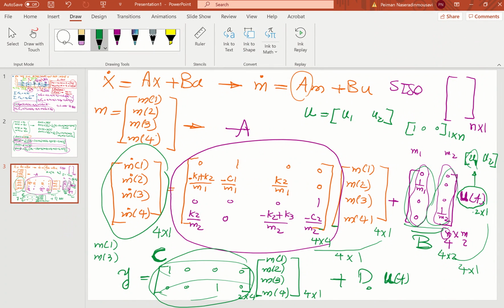U of t, again, boldface is not capital. Okay? Understand? So even when you're dealing with a robotic system, suppose you have a 3 degree of freedom robot, you have multi-input, multi-output, 3 actuations and 3 joint angles. So your robotic system is an LTV system. But again, if you want to make it a very simple case as an LTI system by eliminating the Coriolis parts, your B and C must be like this.